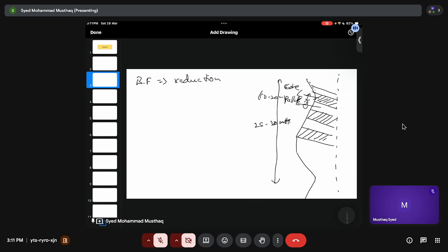Sinter is nothing but an irregular porous mass, formed via fusing different things. Okay. So for example, you are fusing your iron ore and flux and coke. So it is porous but not as porous as your pellet, and also it is in an irregular shape because you are not defining anything, you are trying to just fuse, right? Fusing happens irregularly. And then you crush it and make fines. That's how the sinter works. And briquetting is nothing but you are creating a different shape like bricks. So you can say it's a rectangular shape, and they have much less porosity when compared to your sinters and pellets.